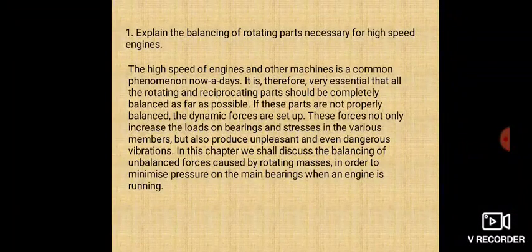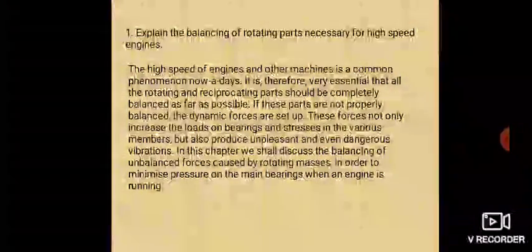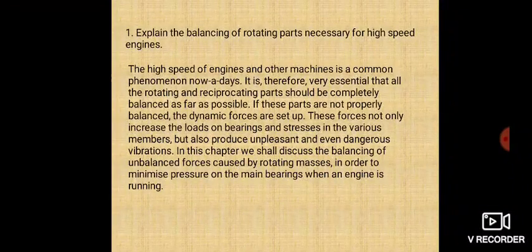If these parts are not properly balanced, then what happens? Dynamic forces are set up. If some parts are not balanced, dynamic forces may be set up. These forces not only increase the loads on the bearings and the stresses in the various members, but also produce unpleasant and even dangerous vibrations. Because of this, balancing is necessary.